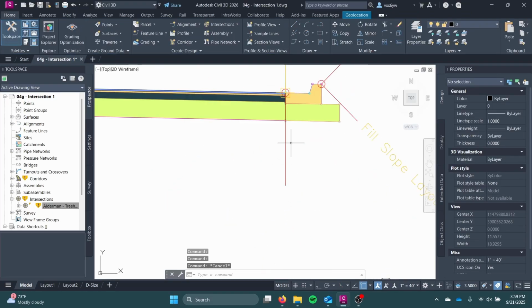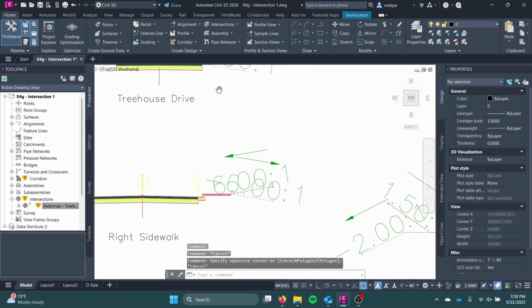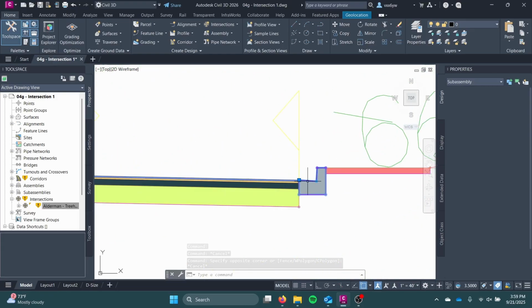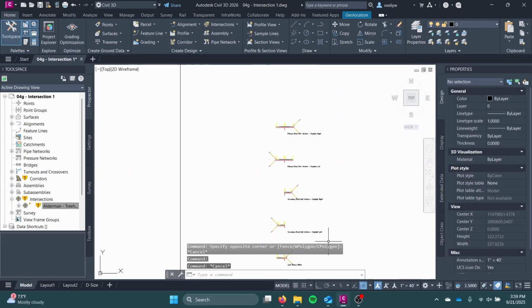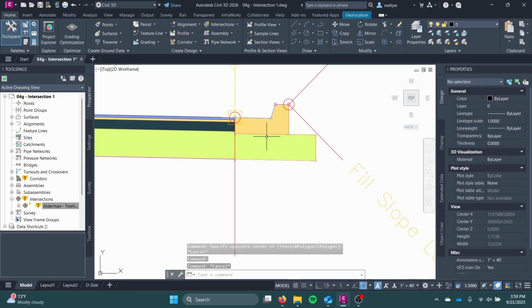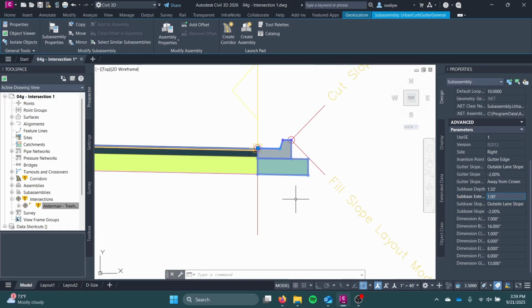And for the curb returns, we know that we actually specified a different width for them. So let me come here and figure out what width that was. Looks like it was just 1 foot, and this is definitely more than that. That's why we didn't see them aligning correctly here. So I'm going to come out here and actually change it to be 1 foot, 1 foot as well. If I can, this is a different section, so I might actually just change it to be the same section that we're using.